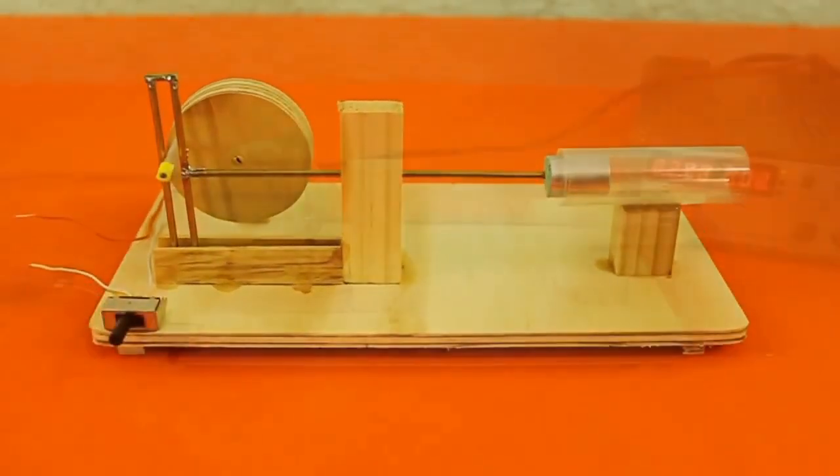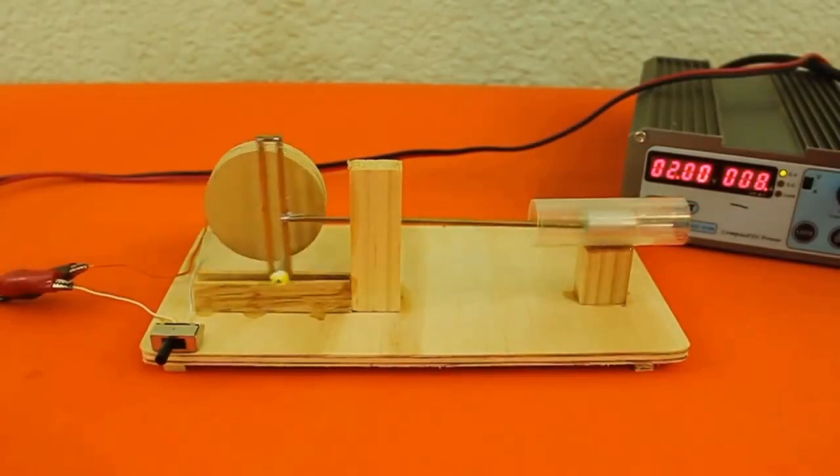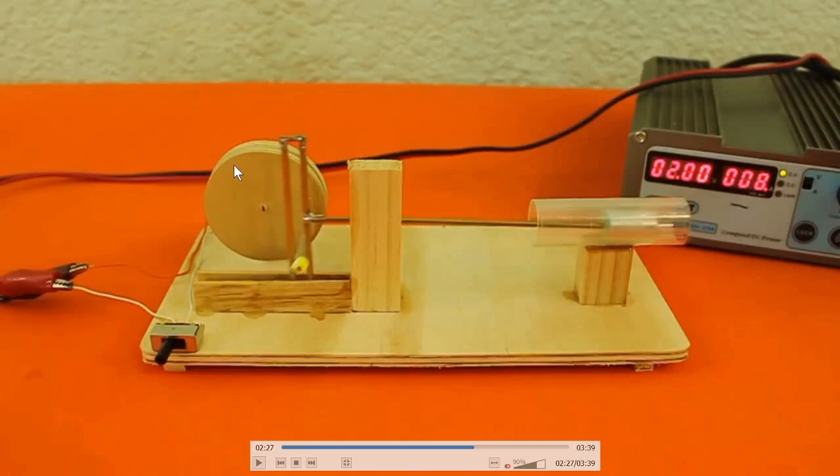we have a Scotch yoke mechanism. Again, this is an inversion of the double slider crank chain. Double slider means we have two sliders. So in the Scotch yoke mechanism, the crank is the same. We have connecting rod and a slider, and it is moving in a fixed path. All are same. The only change is at the end of the connecting rod.